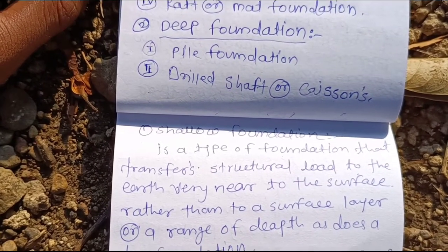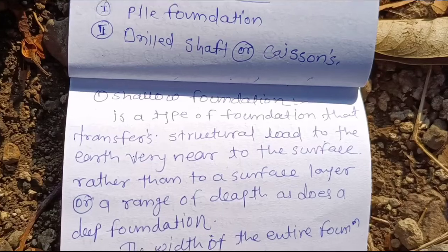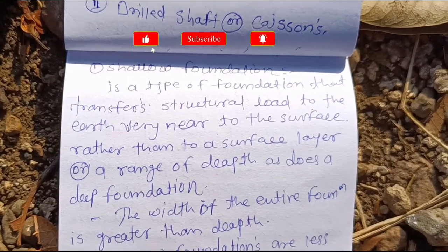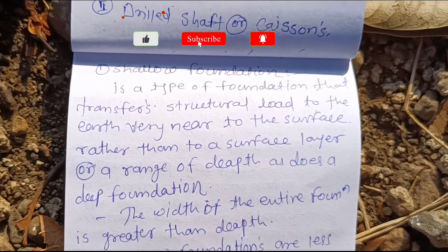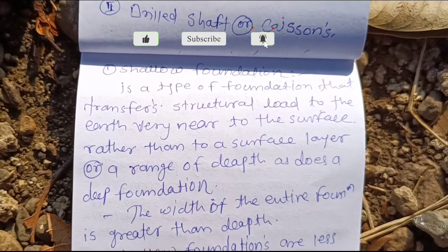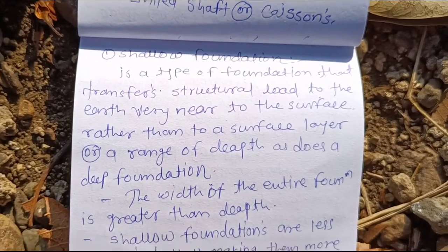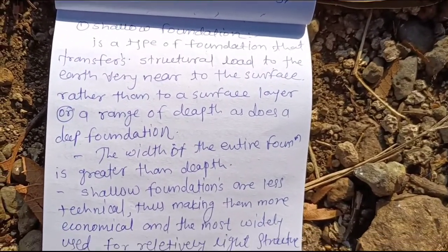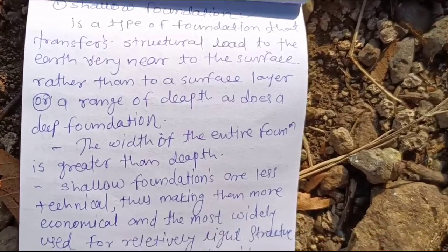Then what is shallow foundation? Shallow foundation is a type of foundation that transfers structural load to the earth very near to the surface rather than to a surface layer or a range of depth as does a deep foundation. The width of the entire foundation is greater than depth.